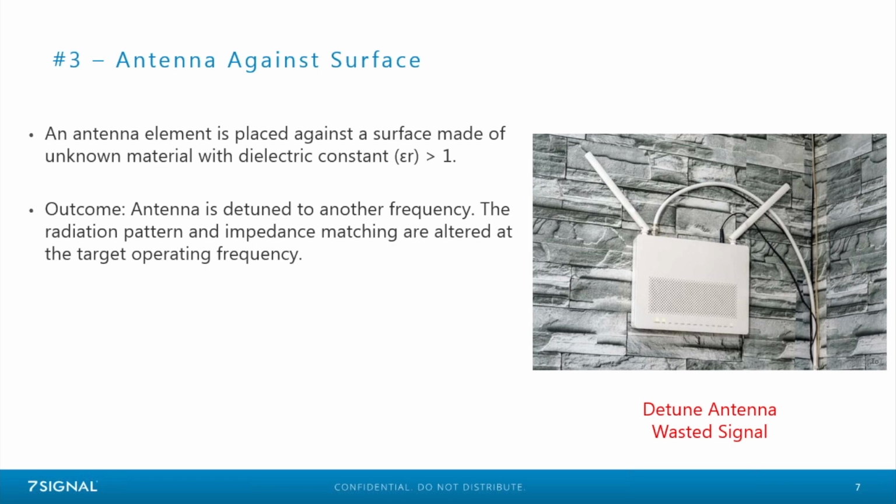The other one, oddly, and I'm not sure why, I see this one in hospitals a lot, just walking down the hall, where they'll just lay an access point on the top of a ceiling tile and poke a couple of holes in it for the rubber ducks to poke through. It's not good for the antenna tuning to be pushed up against those metal rails at all, and it gives it a bit of an amateurish look as well, I think.